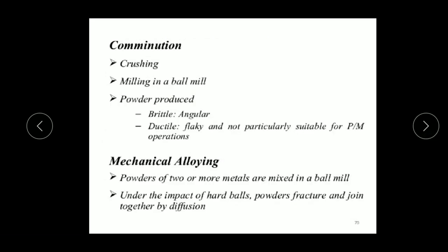Yes, mechanical comminution. Mechanical comminution involves crushing and milling in a ball mill. A powder is produced from different materials: brittle materials in angular form, and ductile materials mainly in the form of flakes, not particularly suitable for PM operations. And another method in comminution,